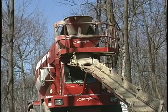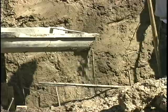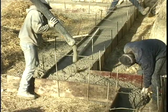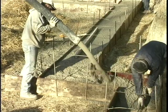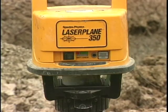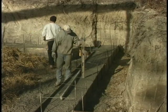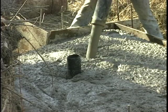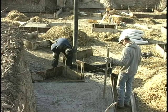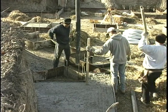Pouring the footing involves filling the form with concrete. The tradesperson making the pour must concentrate on installing the correct amount of concrete to keep the footer level. A laser transit level is commonly used to check the top of the footer pour to make sure it is within accepted tolerances. By lightly placing the level rod on top of the concrete, the laser indicator will audibly and visibly tell you if the top of the footer is too high, too low, or within tolerances.